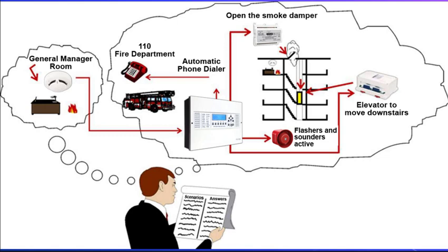Based on messages received from detector, button, or contact monitoring modules in smart addressable systems, it is possible to apply all kinds of scenarios to be determined according to the need via sirens, relay outputs, or relay modules. This is a programming technique based on cause-effect logic.